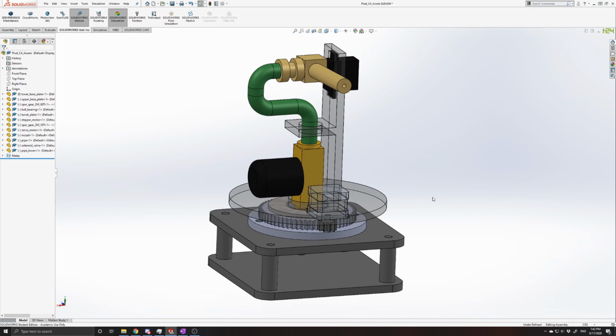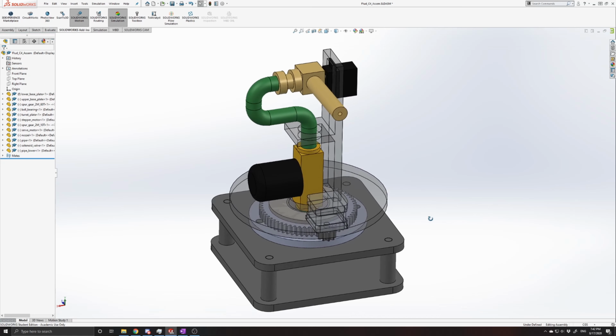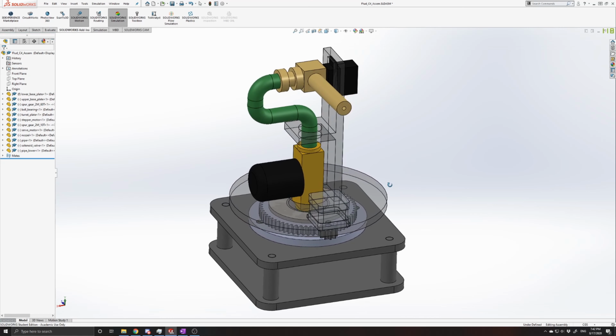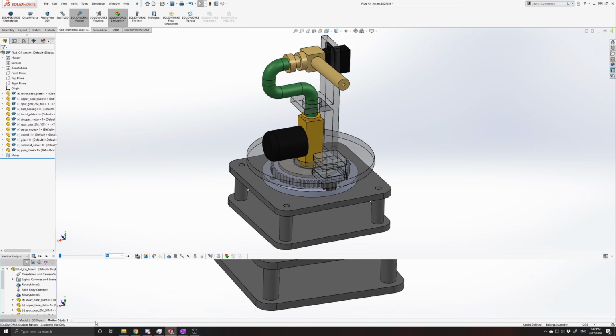We drive this movement through a 1:6 gear ratio with the stepper motor, which allows us to minimize the torque requirements. This also allows for an opening through the center of the device, allowing our water piping system to pass through. The nozzle of the device will be controlled by the servo motor as seen here. This allows the nozzle to rotate about the pitch axis to our required angles. Let's see this in action.